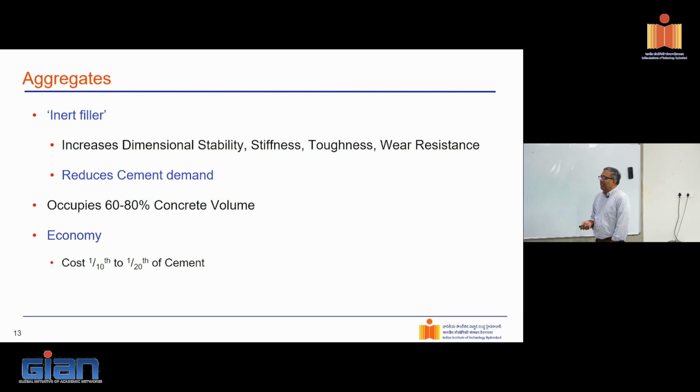What is it that we expect from our aggregate in concrete? The aggregates are treated as inert fillers. Basically, they are inert fillers. So what is their job? Pack the volume, right? So what am I hoping to achieve with the use of aggregate? Minimize my cement content or paste content, right? That is the primary role of aggregate.